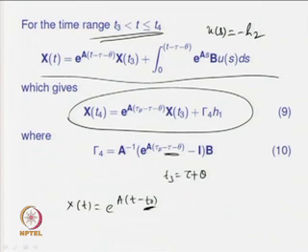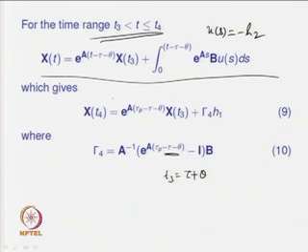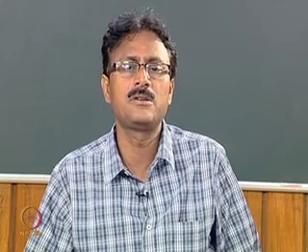So this t0, the starting point for us, is time t equal to tau plus theta, and you are getting the expression x(t4) at particular time t equal to t4. x(t4) is equal to e to the power A (tau p minus tau minus theta) times x(t3) plus gamma 4 h1, where gamma 4 is given as A inverse times e to the power A (tau p minus tau minus theta) minus the identity matrix, times B. So gamma 4 appears over here.